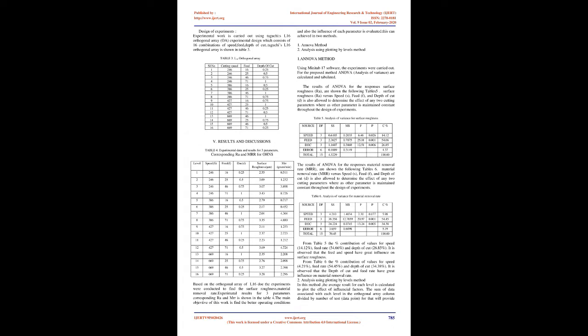Bajik et al. performed the machining process to optimize the parameters for SR in face milling. Test samples made of carbon steel ST52-3 with dimensions 230 x 100 x 100 mm were used in experiments. The parameters cutting speed, depth of cut and feed on machined surface roughness in the face milling process have been examined. The results show that both feed and cutting speed influence surface roughness, but the feed is the most influential factor.